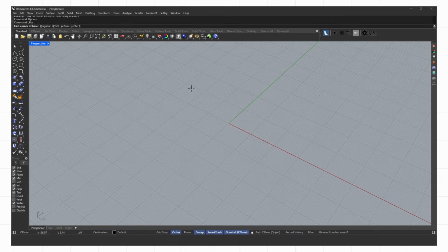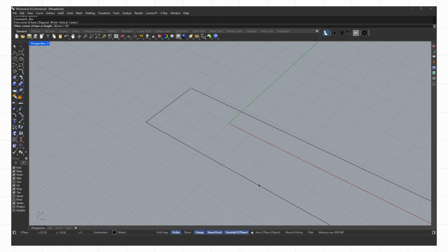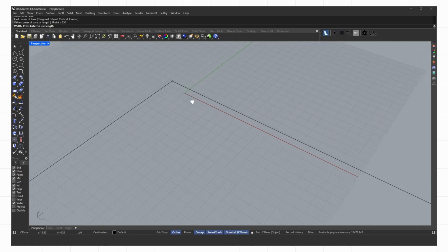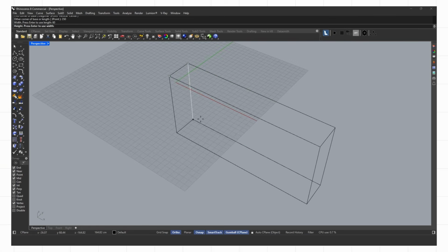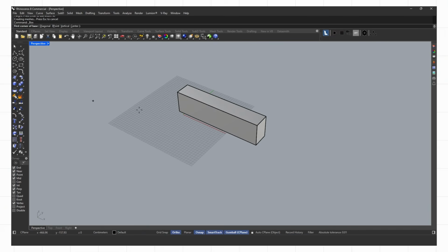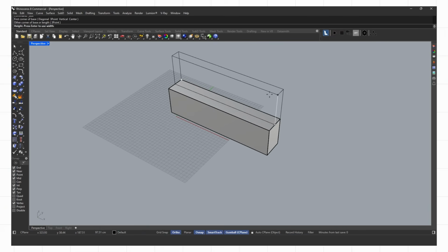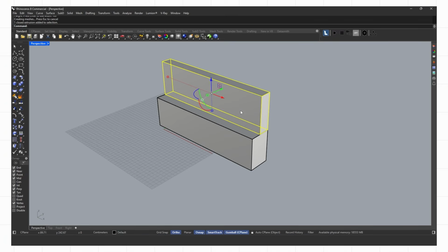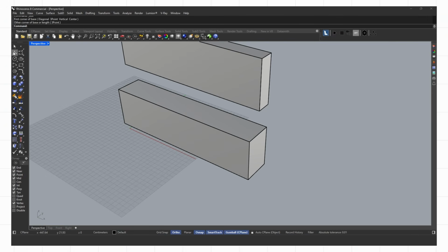I create a simple box that's about 3.5 meters long, aligning with the wall, 60 centimeters deep, and 90 centimeters high. I repeat this process for the remaining cabinets, so the entire cabinet front forms a cohesive unit. While doing this, we also follow the standards. The distance between the upper cabinets and the countertop should typically be 45 to 60 centimeters. In our example, it's 50 centimeters, which is still acceptable. The depth of the upper cabinets is usually 30 centimeters, and we're using the same.